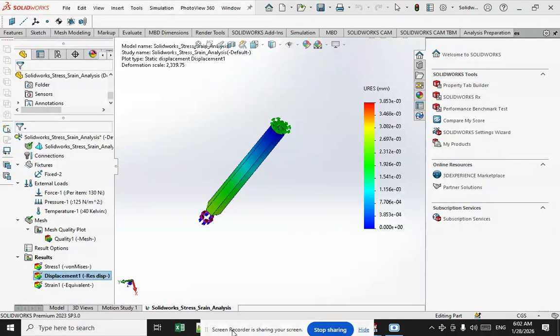The stress that is calculated to develop in a member is compared to the strength of the material from which the member is made by calculating the ratio of the strength of the material to the calculated stress. The ratio must obviously be greater than 1.0 if the member is not to fail.